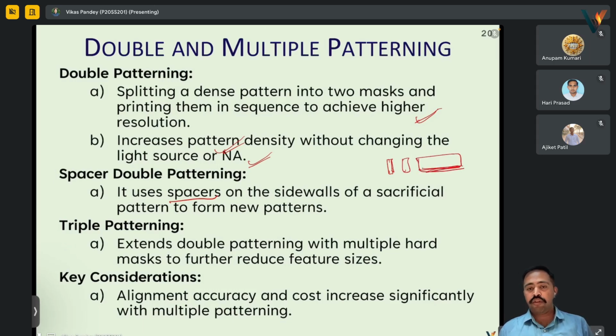And we know that in this area, using the second mask, we will do the patterning, like some extra part we are putting that has to be actually patterned in the second layer. So once we do this, this will be left and that will be patterned using the second or the double mask. And as such, we will get the combination of these two.